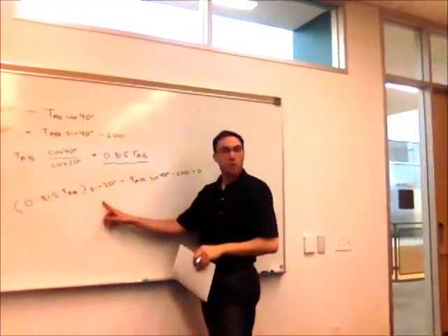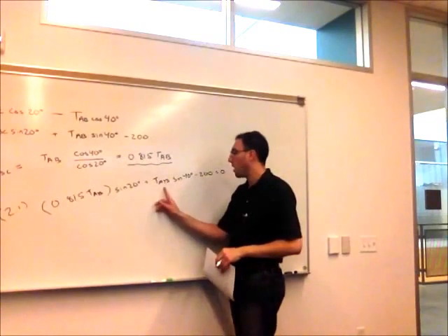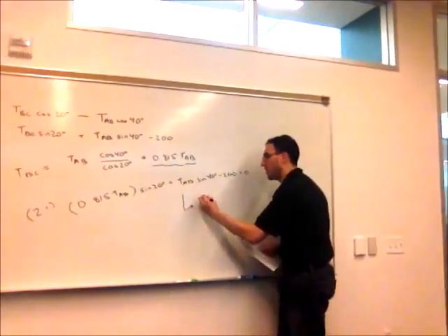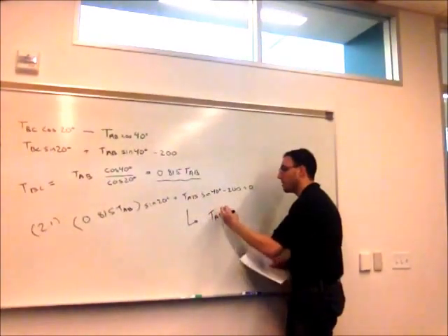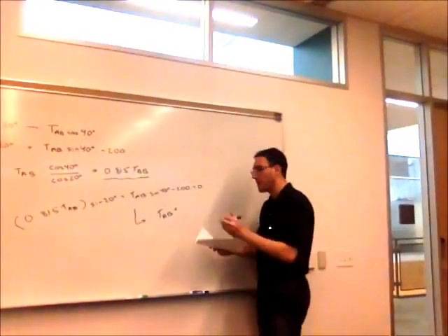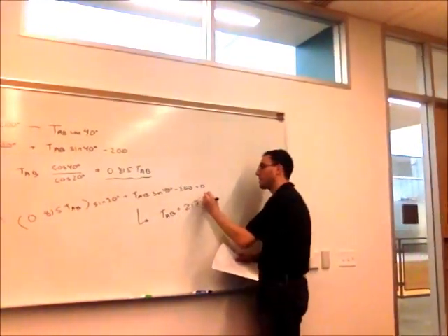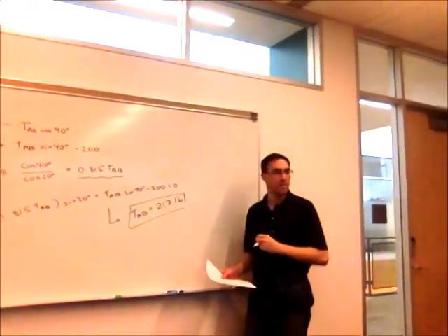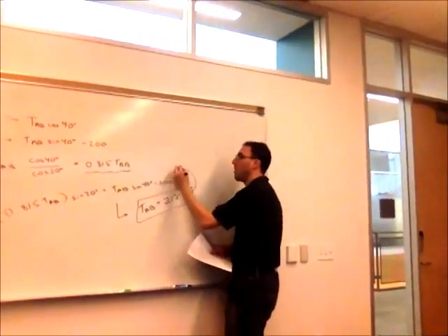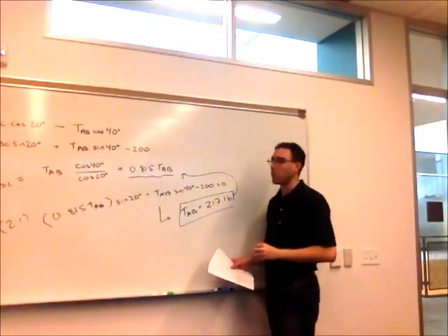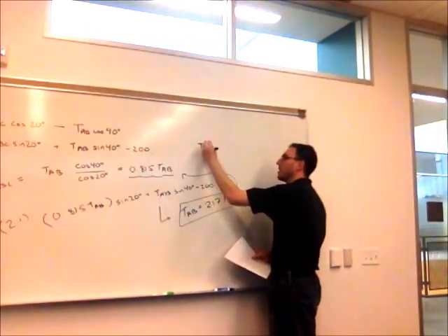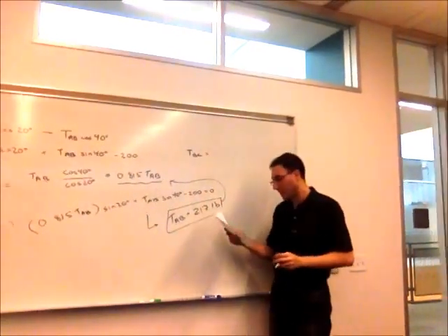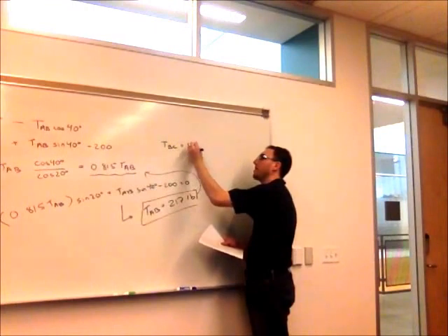So in equation 2.1, what I've done is I now have only one unknown in the equation, so I can solve this for my unknown. So solving this for my one unknown, the tension in rope AB, I get 217 pounds, which is one thing I was asked to find. If I now go back up, put that back into equation 1.1, put the 217 in for TAB, the tension in BC is going to be 177 pounds.